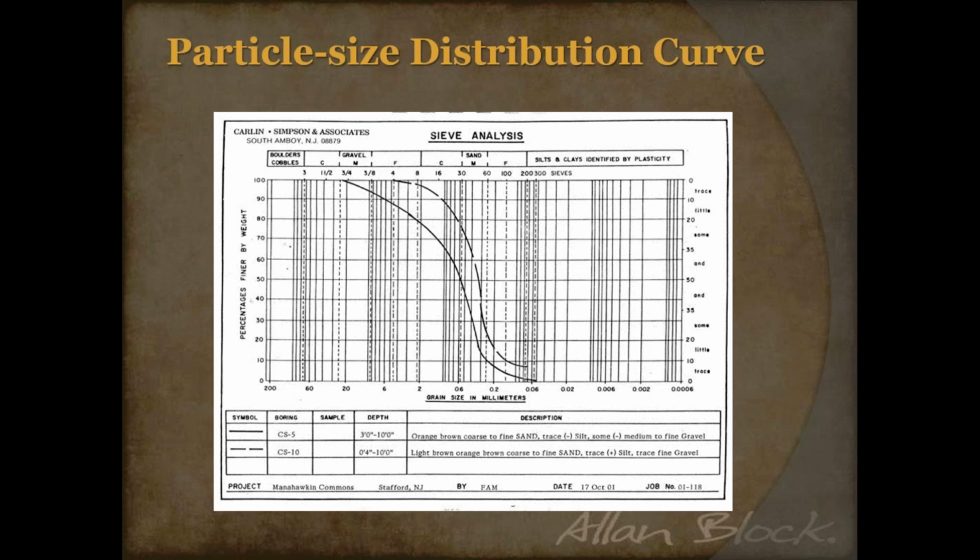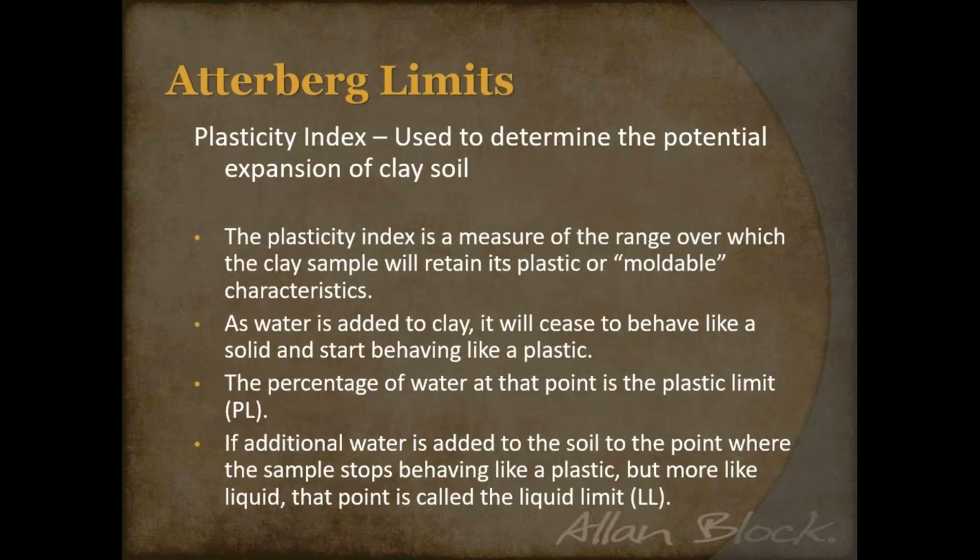So once we know the grain size, now we need to look at the Atterberg limit, especially when you're talking about those cohesive soils, those tight soils where you've got the clays and silts, because not all clays are obviously created equal.